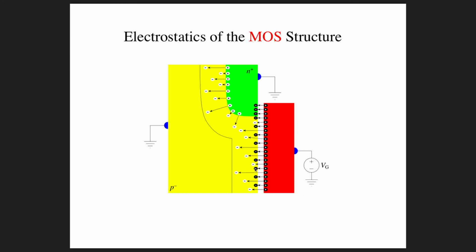And we have what we might call a little band around threshold or perithreshold, where we're kind of 50-50 with respect to the mobile charges versus the bulk charges here, the depletion layer charges. And then once we get a little bit above that, we're in what we call above threshold, where the mobile charges will potentially greatly exceed the bulk charges or the depletion layer charges.